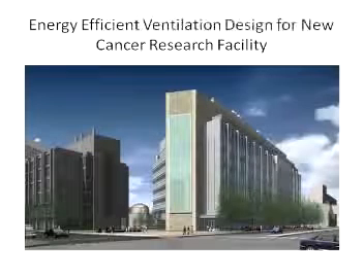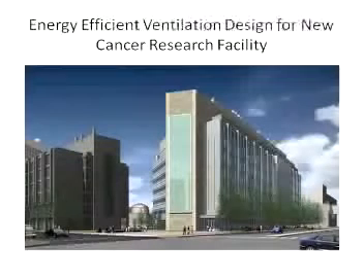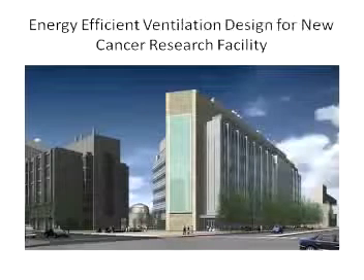So we've instituted that in the new Koch Center, which means a very substantial saving in energy, both the heating energy in the wintertime as well as electricity to run the fans. So the electricity savings may even be more than 20% for this particular building. So a good example where some very simple research has already shown up in new building designs on campus.